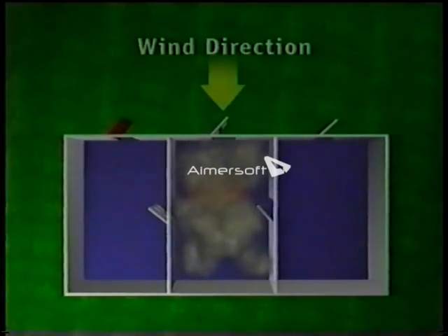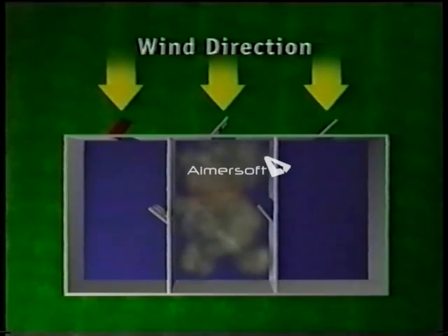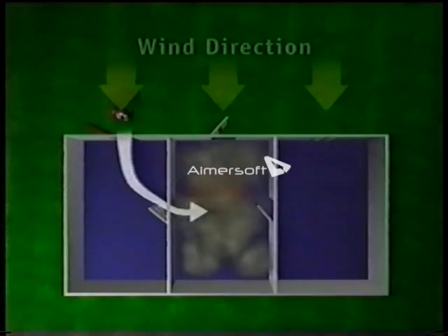When using horizontal ventilation, and the only suitable openings are all on the same side of the building, the use of natural ventilation may be ineffective. This is because the pressure of the prevailing wind will act equally on the inlet and outlet vents. This is one example of when forced ventilation can be used to create air movement.